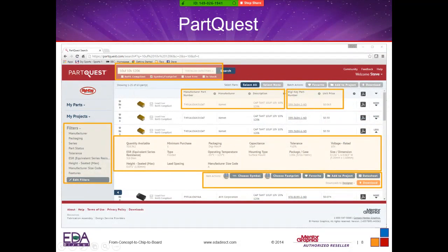So you can download those and bring those right into your library. They will be fully loaded with the properties that come with it. You will have the ability to add your own properties as well as them filling in the necessary properties that DigiKey has allowed, anywhere from manufacturing part numbers to the description of the parts, to operating temperature, and then should you require any other properties, you can add those as you bring them into your library.